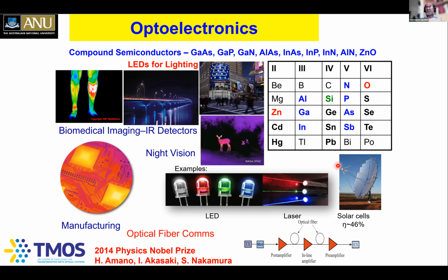And then you can generate 500 to 1,000 suns of intensity of light there. So people want to make use of these most efficient solar cells because the system cost is so high. Also, they are tracking the sunlight as well. So that's where 3-5 semiconductors have been exploited as concentrated photovoltaic systems.